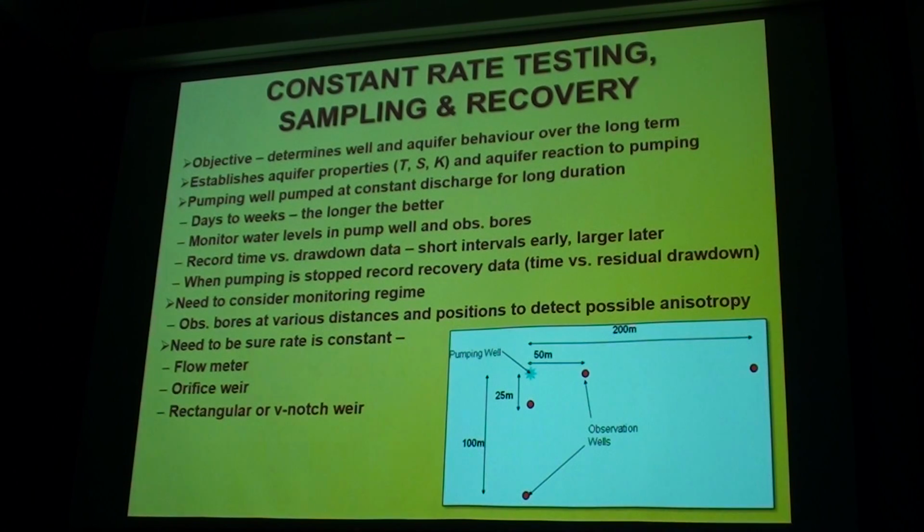And basically, the pump test contractor will live on site the whole time this is going on, because he needs to be there in case anything goes wrong. Okay, if the generator dies or the pump dies or something, he has to be there to sort things out really quickly, because that effectively ends the test. He has to wait till everything recovers and start the test again, because the contract will call for a specific length of test, and it has to be done if they've signed it.